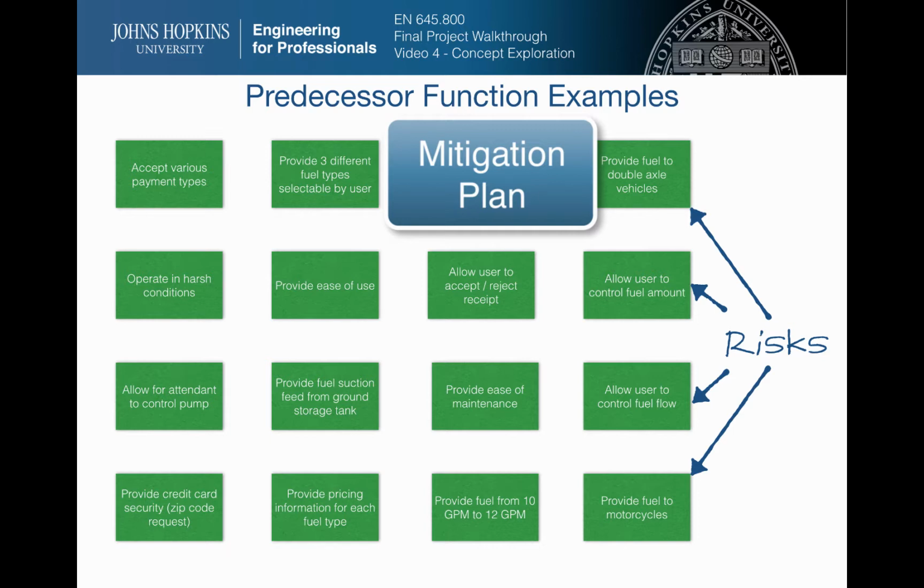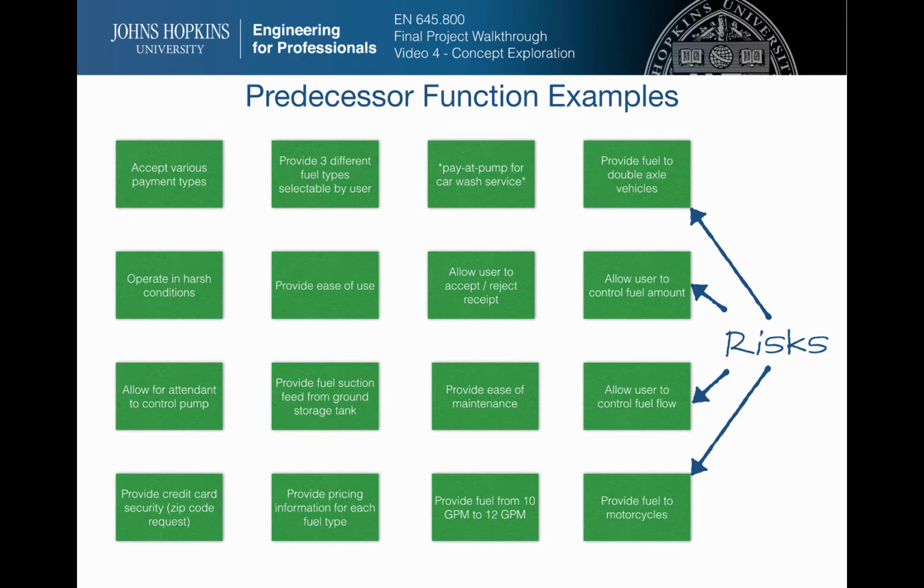This is also a risk. Assuming that I have down-selected to the robot arm, another risk my system will run into are the vehicles that have refueling ports behind their license plates, or in the back of the vehicles, or otherwise in atypical locations. I probably should do a little bit more analysis if this solution is chosen to try to evaluate whether or not it's worth leaving alone or accepting, or trying to mitigate it through some design features.